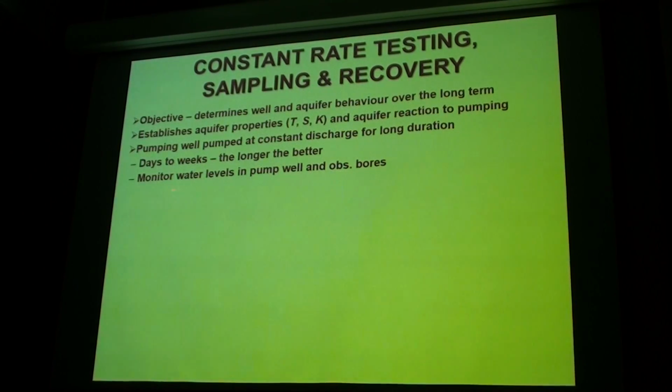You're going to be monitoring water levels in the pump well and the observation bores, as many as possible. Okay, some existing observation bores, so those people's wells that you've talked to before, you might be able to use those, see if they're affected. You'll have constructed some yourself as well. But you've got to analyse all that data to better quantify your aquifer. The aquifer is probably not homogeneous. Okay? It's going to be different in different directions. So if you've got data coming from different directions, it's really, really good.